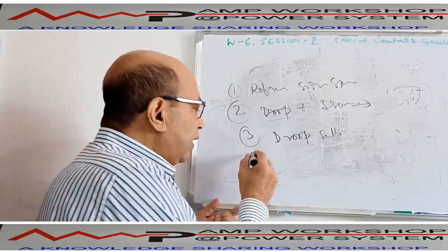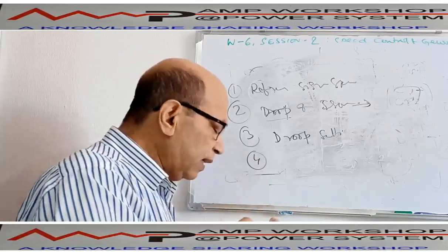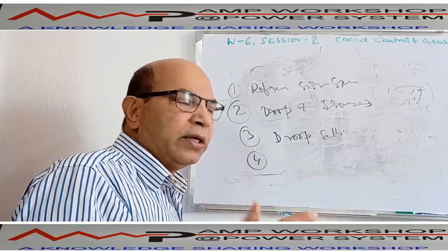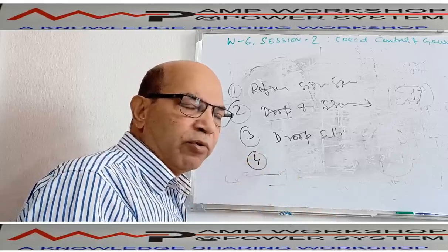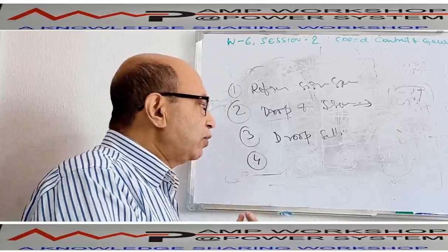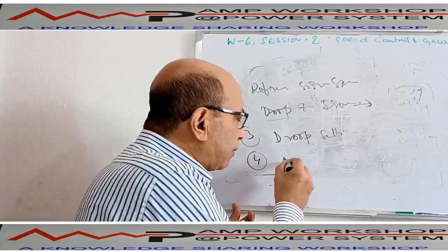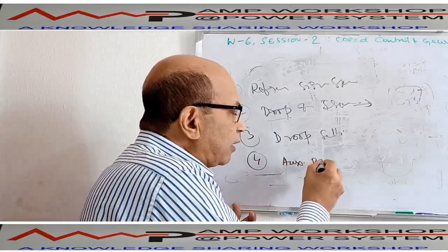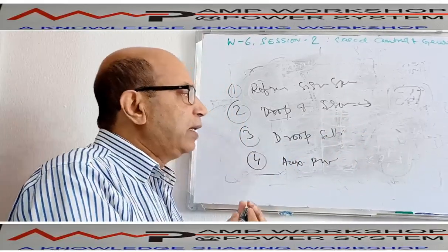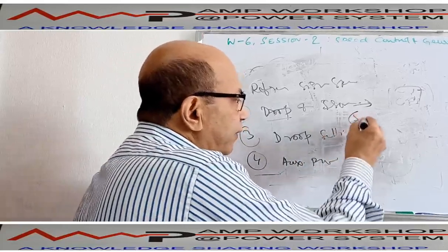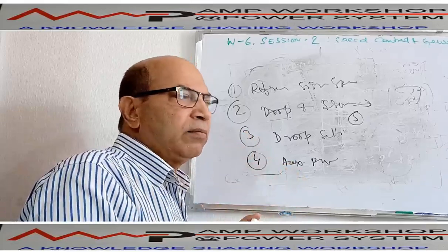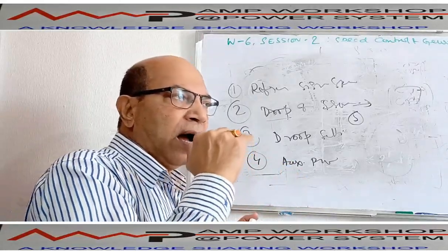That is another setting. Number four setting is the control voltage. Maybe in the same governor there are multiple voltages available. You can give the governor 48 volt DC, 24 volt DC, or it is possible to give both AC and DC signals. So that setting will be there. The auxiliary power supply setting should be there. Whichever supply you have to give, accordingly you have to set the switch.